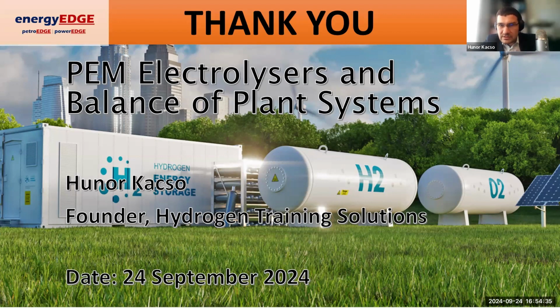What will be the efficiency and purity of a PEM electrolyzer? The voltage efficiency we've talked about, and for the purity, depending on your dryer, you can easily achieve grade E hydrogen for fuel cells, and you can easily get to the point of 1 part per million, 1 ppm. I'm talking about 1 part per million water vapor.